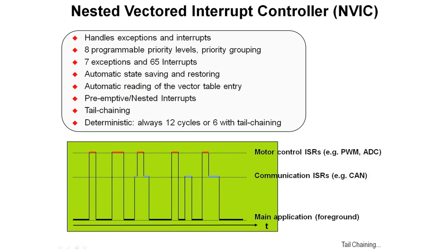One of the first rules that you learn when you're programming interrupts on a microcontroller is to not nest interrupts. And one of the first rules that you break is you nest the interrupts. You need to get to a very low latency motor control or a temperature sensor or some device very quickly, and you have other interrupts that are too long.